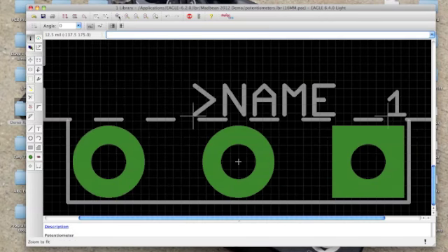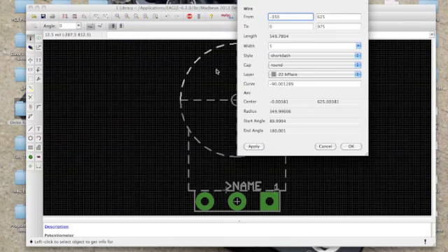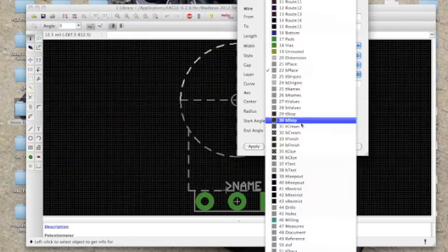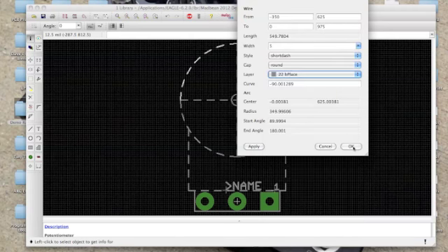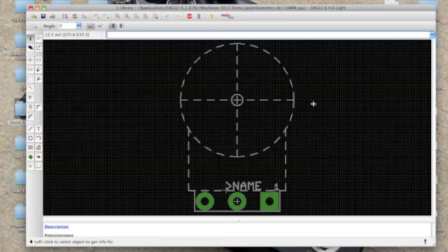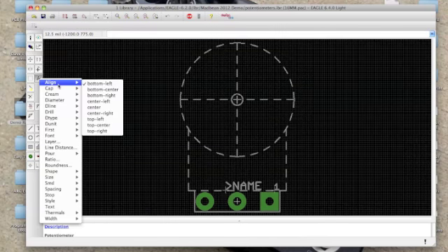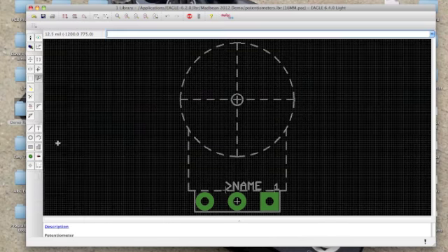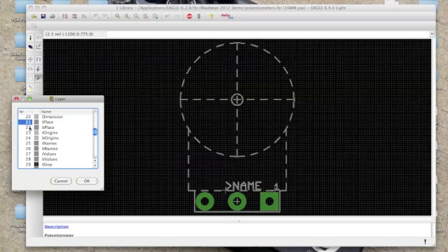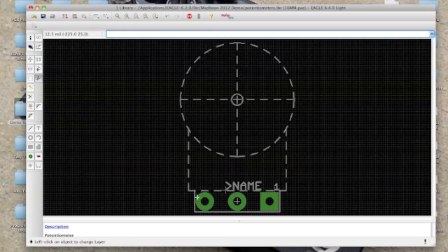But if I zoom out here a bit and I specify this line is on the bottom place line, and I hide the bottom place layer when it's silk screened, what ends up happening is this line right here gets printed, but all this stuff gets hidden. And this is another thing you can do by properties. You can press layer here, and I'm going to switch everything to the bottom place that needs to be. So for example, this line, this line, this line, all of these lines that I'm touching are now getting switched. If they weren't already there, they are now on the bottom.